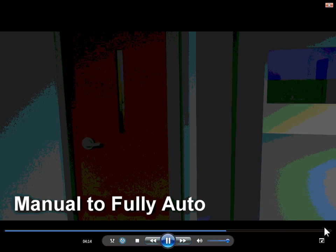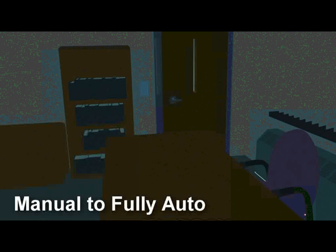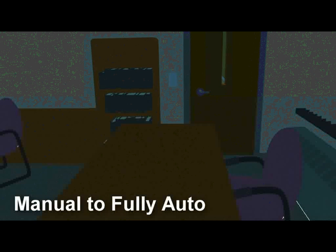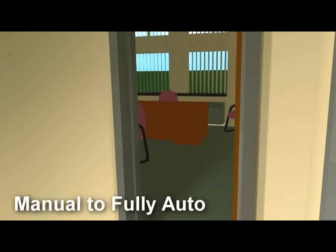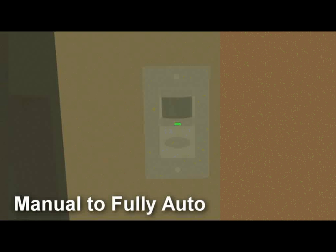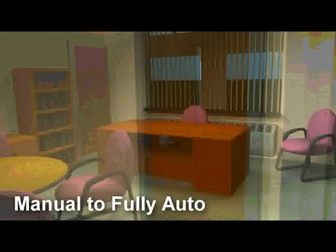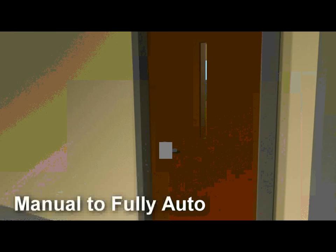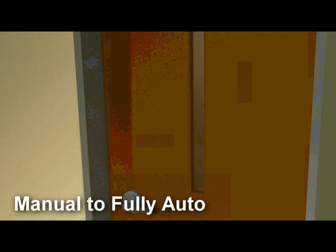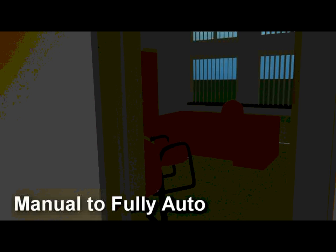Manual to fully auto. This powerful feature maximizes both occupant convenience and energy savings. To prevent short non-occupant visits, such as those of a cleaning crew, from activating the lights before the office occupant arrives, the lights are held off each day until an occupant manually switches them on. When switched on, the sensor assumes fully automatic on-off operation, thus preventing the occupant from having to switch the lights on again each time they return to their office throughout the day.